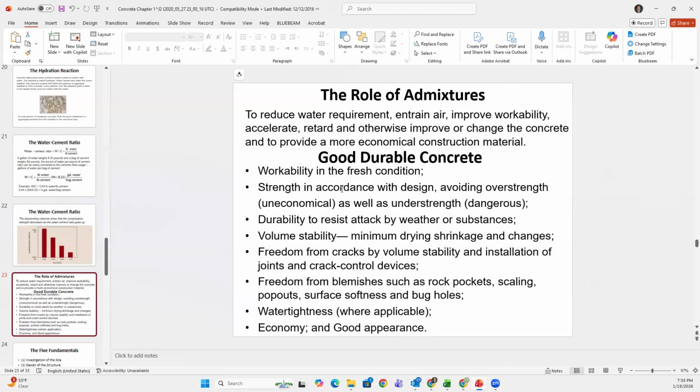These concrete areas are not porous. All the rainwater through the storm drain goes to the ocean. It doesn't do any good for the local trees. So in order to cultivate local trees, good agriculture and all that, porous concrete can serve a lot. And now it's a part of the code that agencies like Caltrans that pour a lot of concrete, by law, have to use porous concrete.